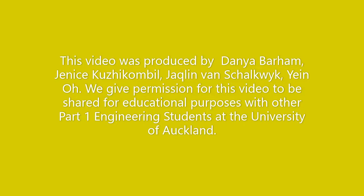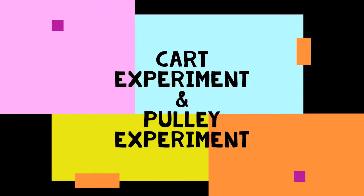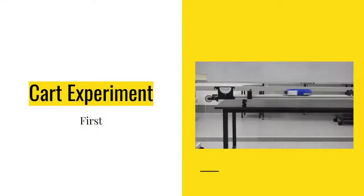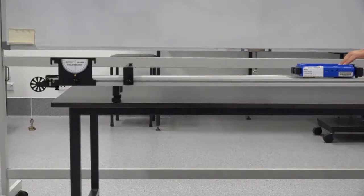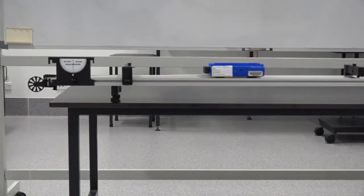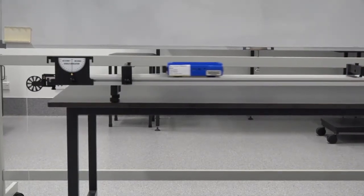In this video, we have analysed the cart experiment and our own experiment of a pulley system to explore various dynamics concepts. The aim of this experiment was to find the masses of the cart and the bumper from the data supplied of the two runs. We selected relevant data sections for a series of calculations necessary for estimating the masses of the cart and the bumper.